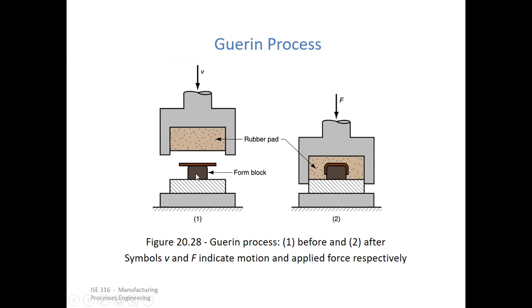You can see this is kind of a support, or backing, because once that rubber pad touches the sheet, the sheet will have to take the shape of the foam block because of the pressure from the rubber pad. So the sheet, as you can see, is taking the shape of that. The profile of that foam block is now upon that sheet.